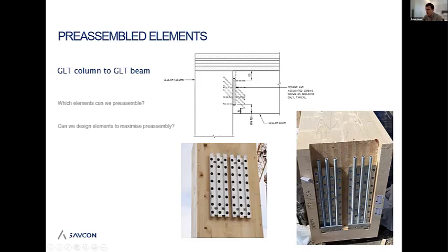So it's quite important when you're talking about these screws. What is the benefit to us on site? It's the time on site. That's your no-brainer, by how long it's going to take to put those in. It's also the double movement of materials. If that's already pre-installed, we can lift that straight off the truck or straight off the pile and install it straight away, as opposed to taking it off, putting it onto a trestle, and then pre-installing, installing those screws, and then taking it from that trestle back to the installation. So there's multiple facets why pre-assembly is important.